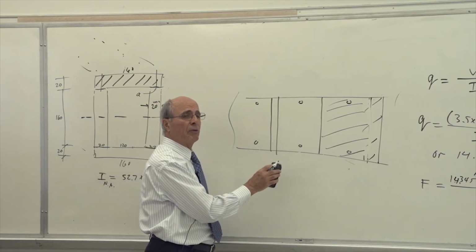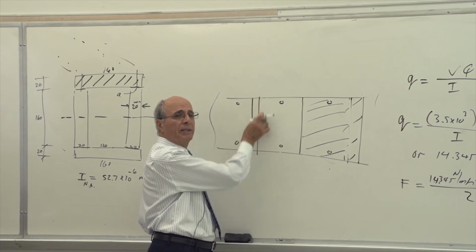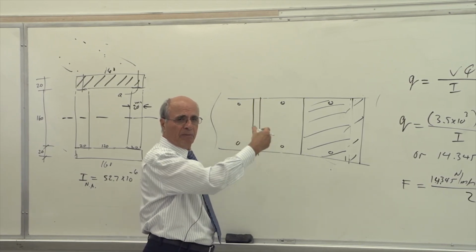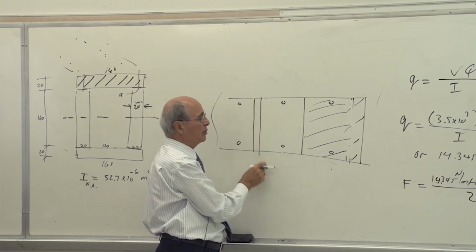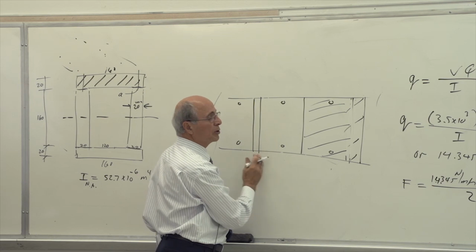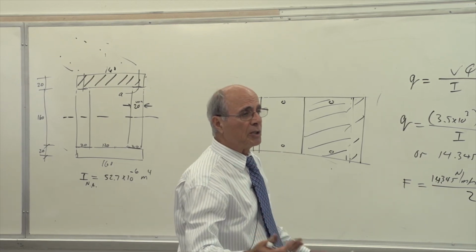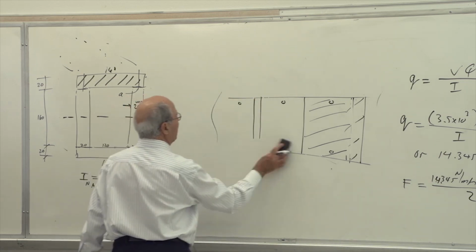Everybody, is that clear for everybody? So all you calculate is the Q, which is the amount of force per one. It could be millimeter or inch, depending on which system. You calculate for one, which is the shear flow, from the top view. Then you multiply it by spacing, then divide by nail, because it depends on the scenario. Notice that I can change that suddenly.